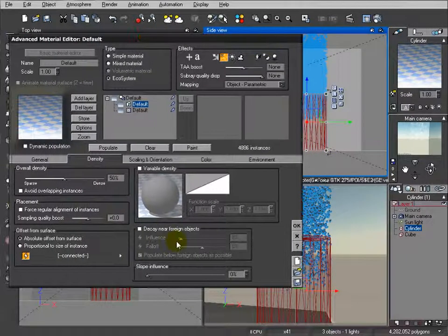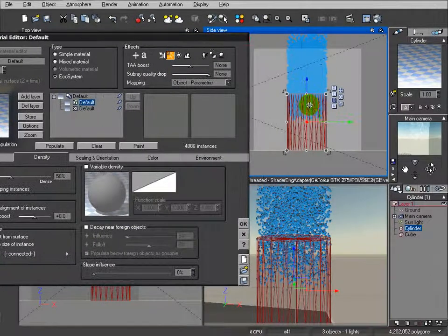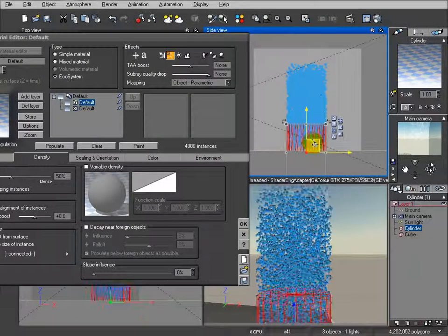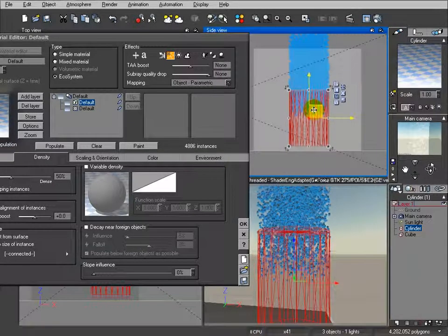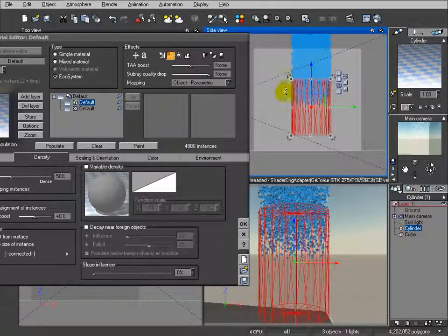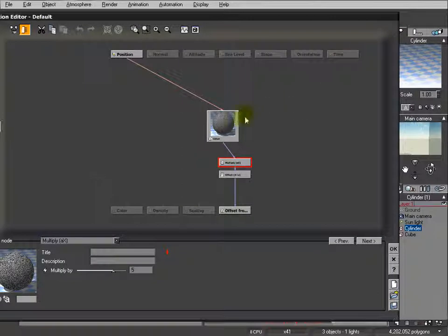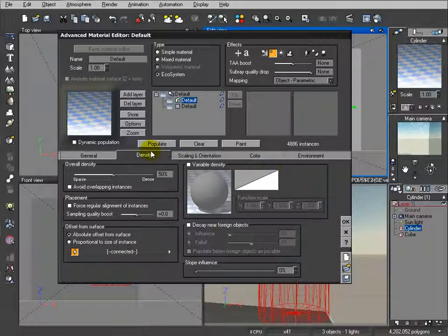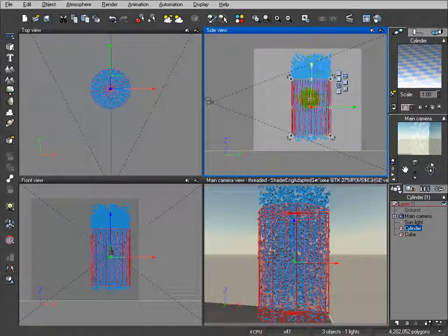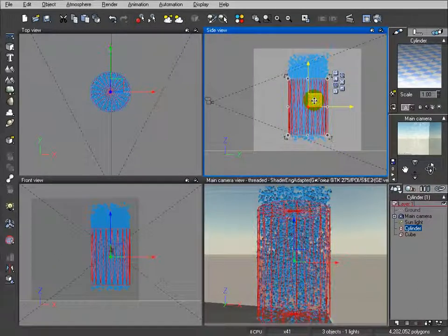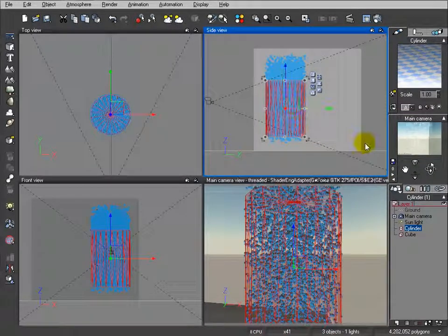Okay, next what I want to do is actually realign. It's not a big deal right now, you can even modify this when you preview, but sometimes it is helpful when the cylinder is representing maybe the middle or other area where your bubbles are located. For that reason, we will use the offset. In the offset, in this case, we'll set it to minus maybe 3. Let's click OK. And here you can see we already offset a little bit below. I kind of like it, because it represents the bottom of my cylinder. In this case, I can modify it. So let me go ahead and move the bubbles a little bit closer.